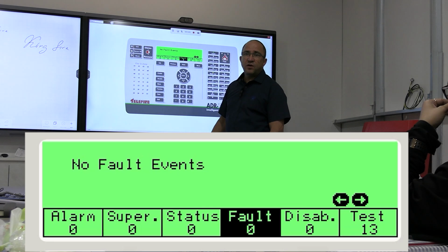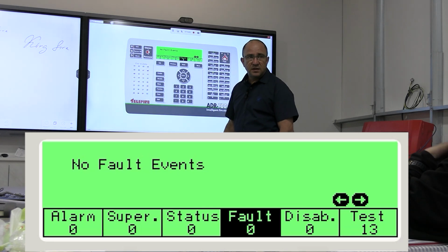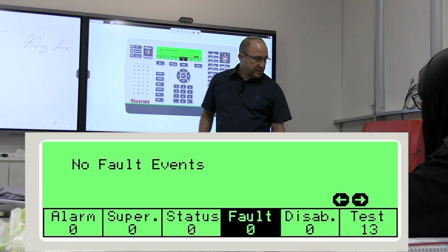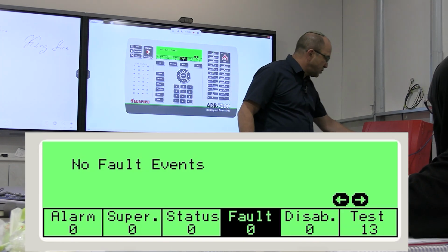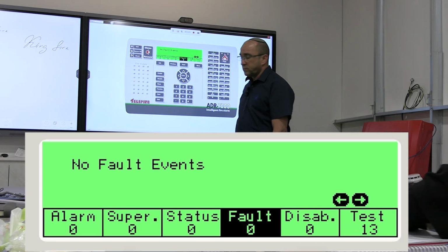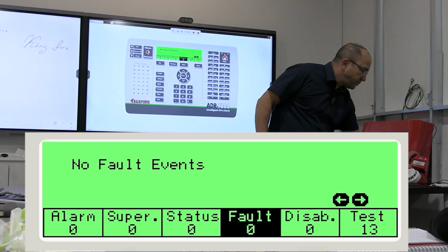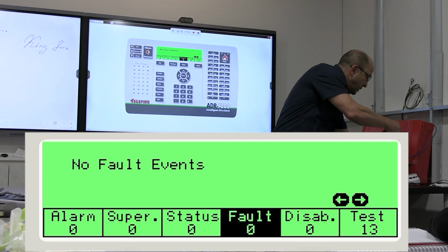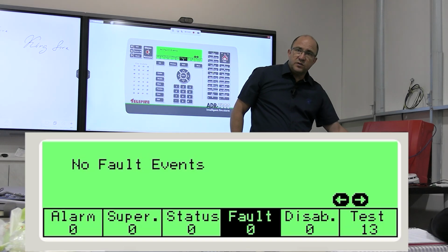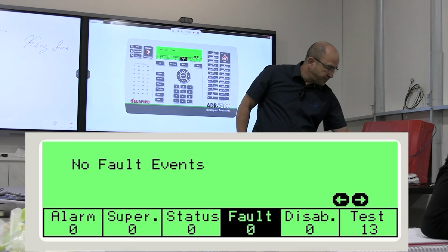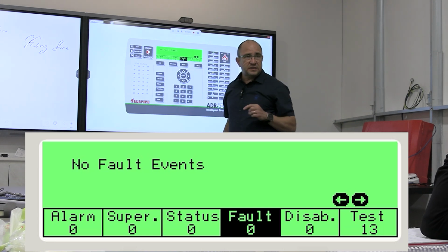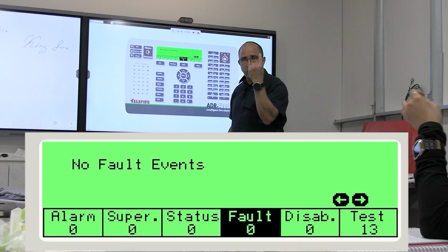Test. We have 13 devices that are in test mode because this belongs to loop number 1. Since I don't have a magnet, I will test this push button. Have a look. Okay. Now I will clean it, and after 10 seconds the LED will switch off. That's it. Okay, so I already checked and whatever. If I go later on inside the reports, I'll see walk test 1.